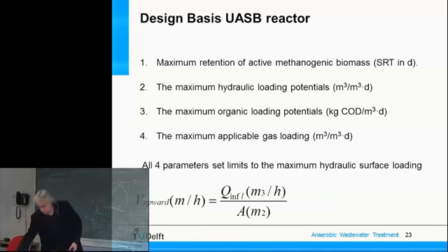Now, we are dependent on the amount of effective biomass that we have here in order to convert. The biomass, the bacteria, are the biocatalyst. In activated sludge, we have aerobic bacteria, then you need aeration. Here we have anaerobic bacteria, and the amount of sludge mass that is able to convert the COD into methane determines the volume of reactor that we need.